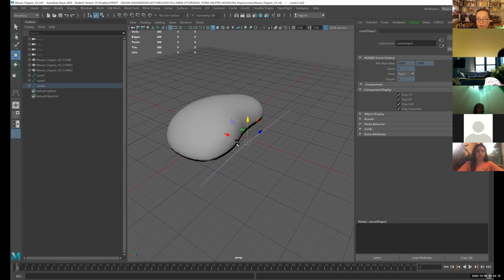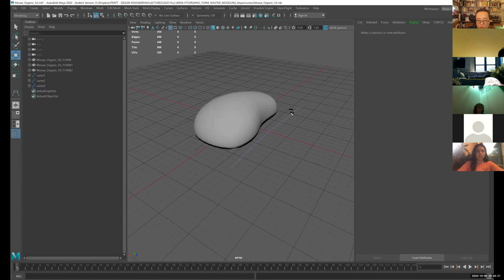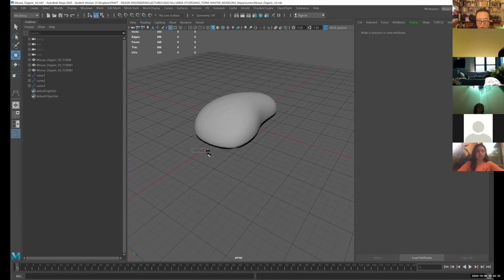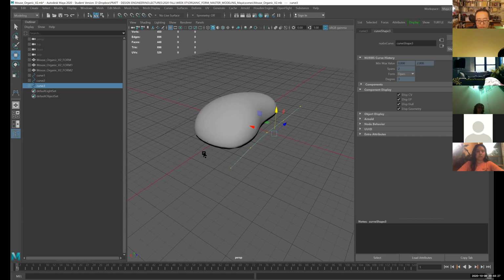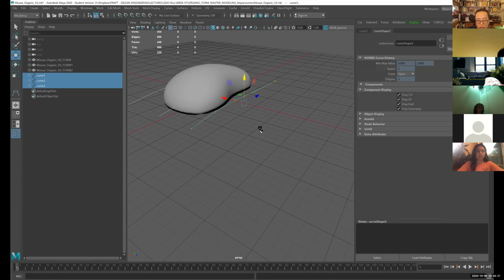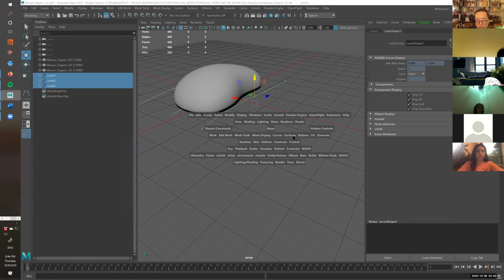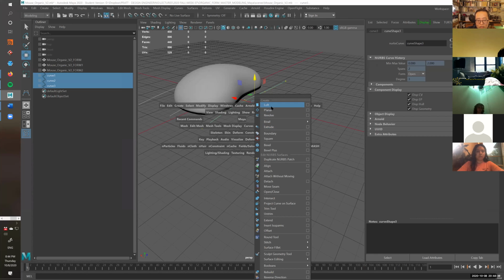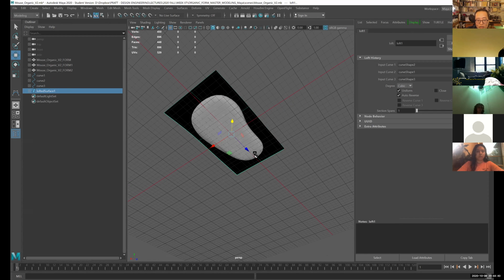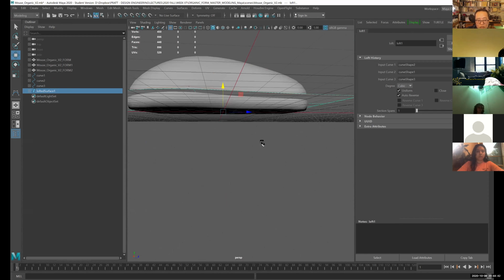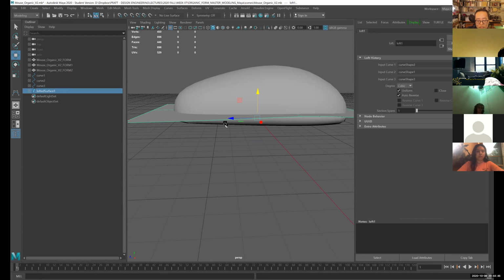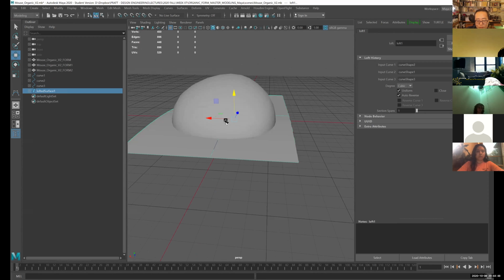So now with these three curves in space, what I would like to do is create a loft surface. There's one, two, three curves. If you select them in order, 1, 2, 3, you can go into Surfaces. This is the space bar, okay, to bring up the menu, and then say Loft, and you have a surface here. So this represents the mold parting line, the part break line that will separate the top from the bottom.